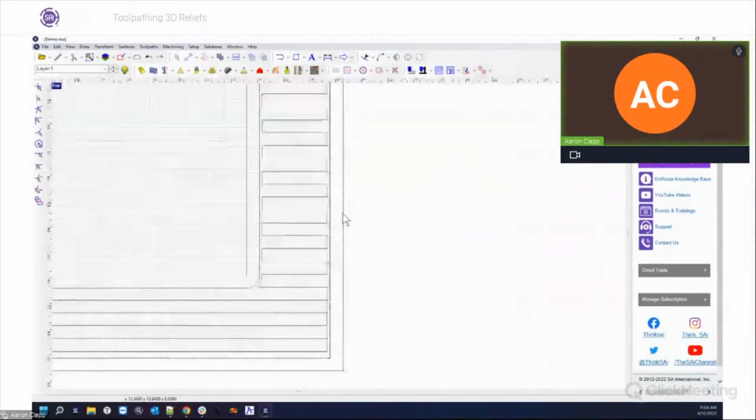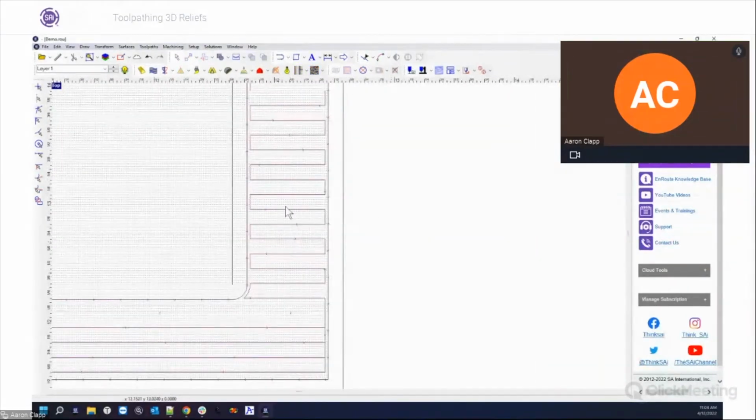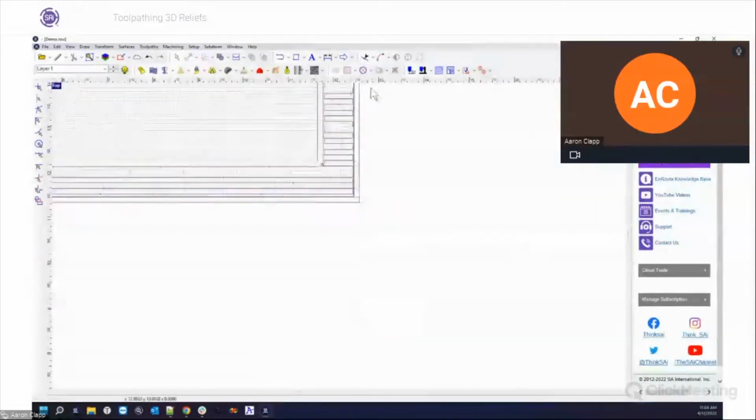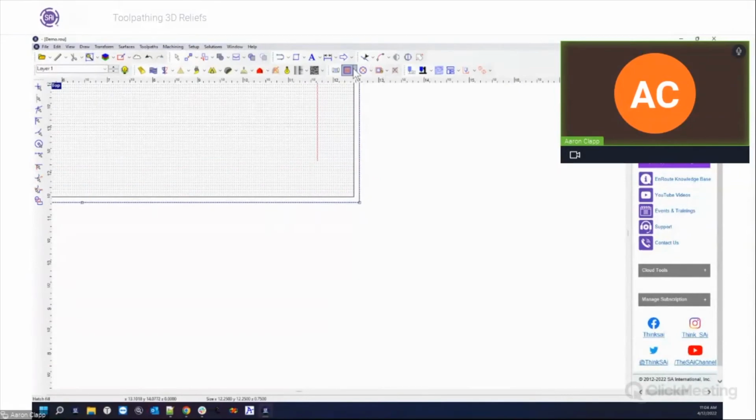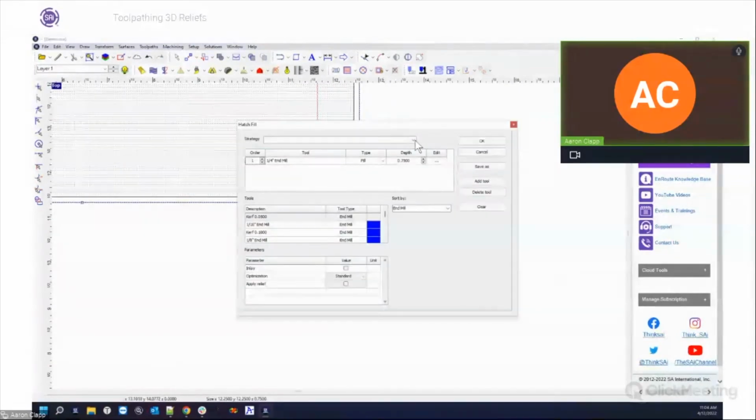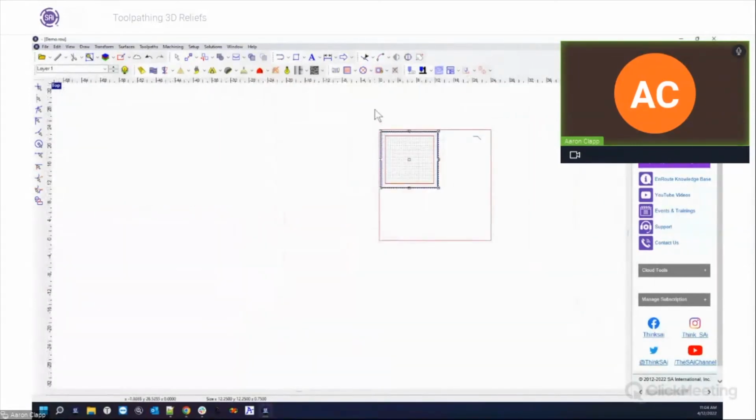So now I can push that toolpath right up to the edge here. Actually, in this case, I made a mistake. That's my fault again. Because I offset already, I do want to turn off the overlap. I just don't want it to be quite that excessive.